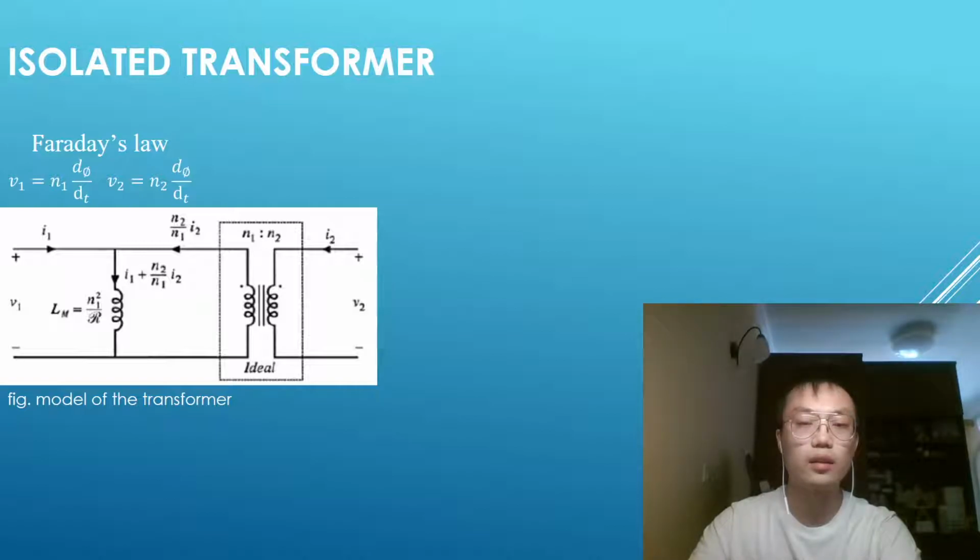The transformer is quite large, so noise will not be induced from the primary coil to the secondary coil output, so it can reach a clean power supply. In addition, the conductive part of the casting is connected to the ground, which can reduce magnetic leakage and electromagnetic interference and ensure the safety of the output end.